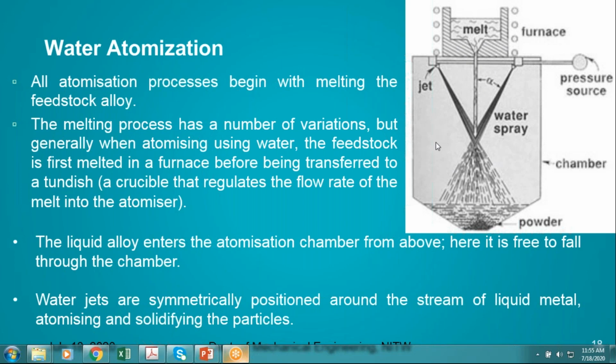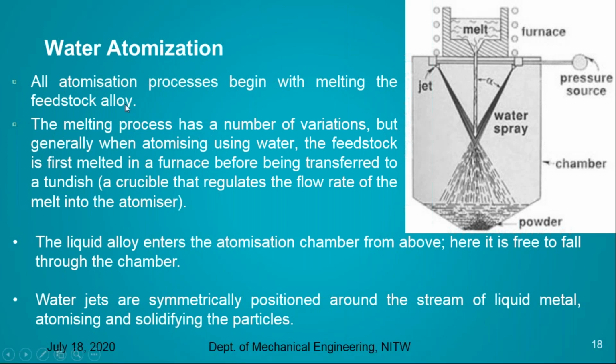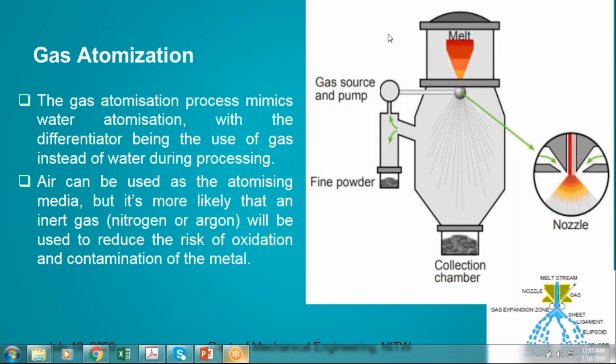This is the atomization chamber. The water jets symmetrically from both positions around the stream of this liquid. It breaks the stream into small ligaments, and the powder particles solidify to form the powder. This is how the atomization process happens.